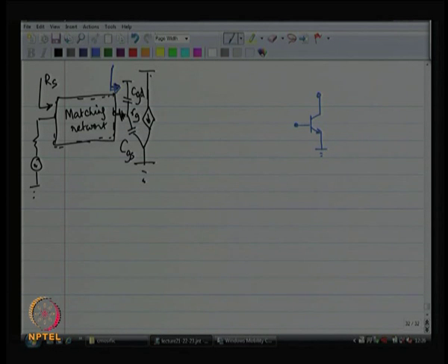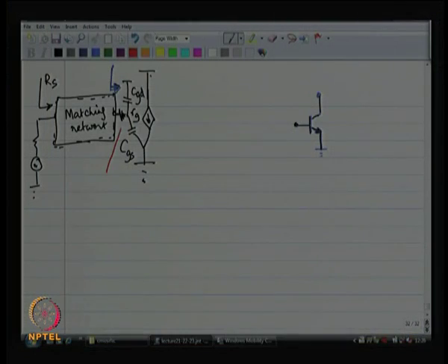I will not confuse you, but if you do use a bipolar junction device, then you do see a base resistance, but that base resistance is not a resistor. This gate resistance is a resistor, it is coming because of the presence of a resistive gate, distributed resistance on the gate, poly is there, polysilicon, it is coming because of that, it generates noise, it consumes power. The gate is going to consume power and generate noise.